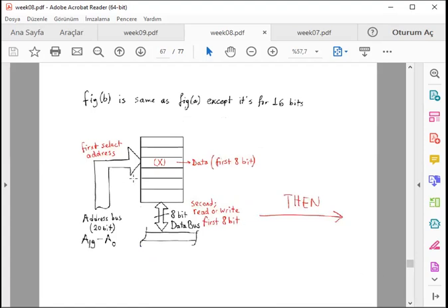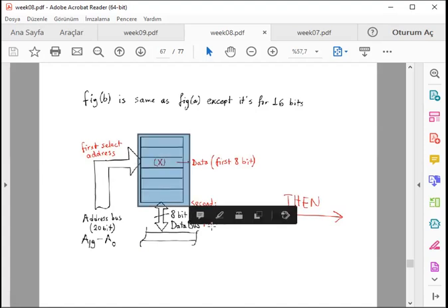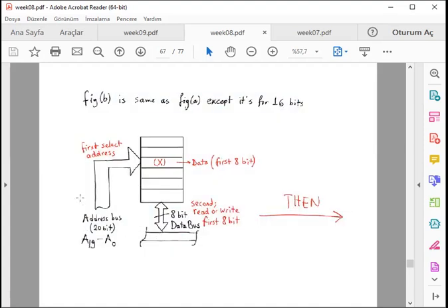So if we want to look through a simple flow chart of the odd memory bank with BHE, now any memory location in our microprocessor chip, since all the memory locations are byte located, we either write a byte to a byte location or write 2 bytes into 2 consecutive locations, okay? So this is the normal byte to byte writing.